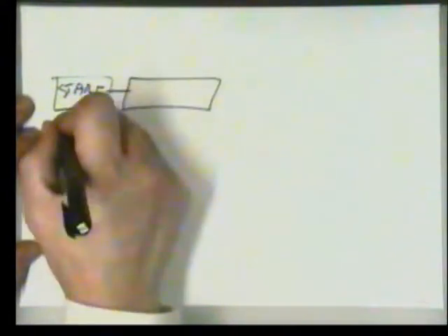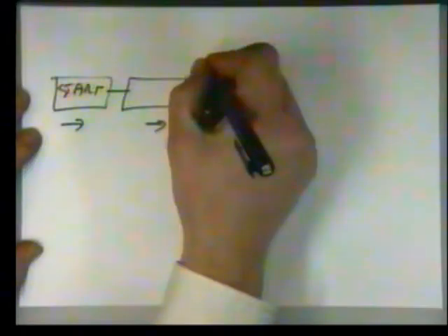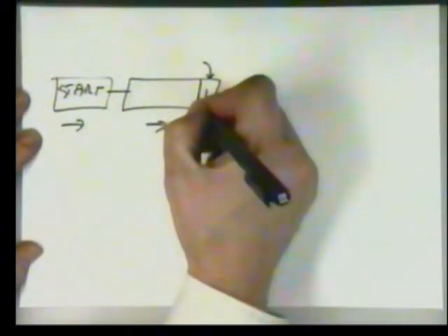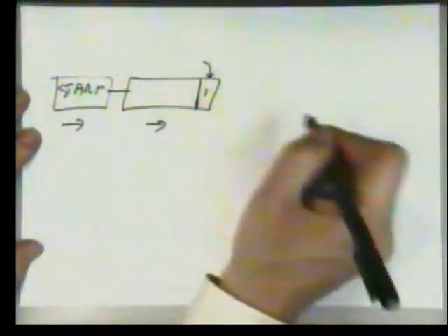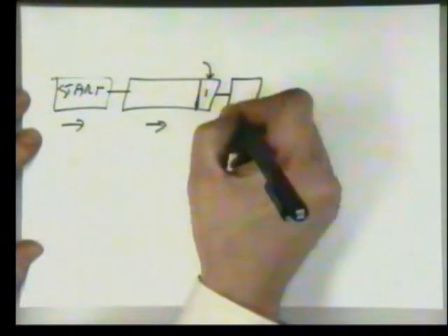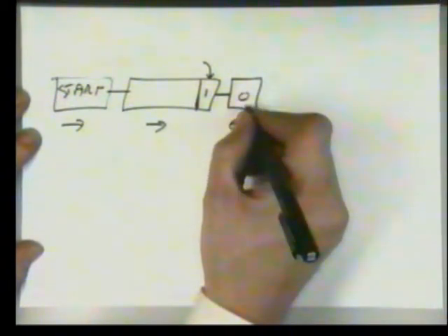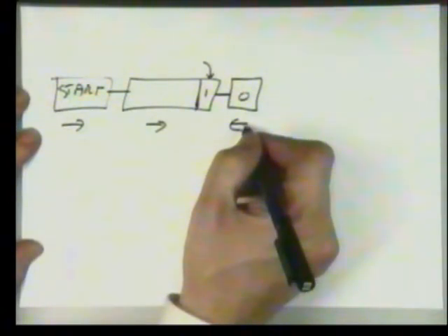What about a read operation? Well, with a read operation, we have start, as before. That goes master to slave, then we get a command master to slave, but this time the read write bit is set to a 1. That means the next operation is a read from the slave back to the master. What happens? Well, first the slave acknowledges receipt of that command as before. Every byte transfer, there must always be an acknowledgement bit that comes back.